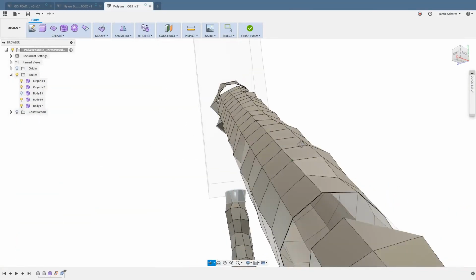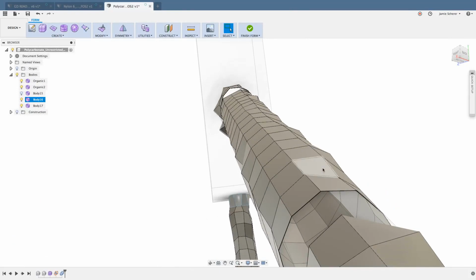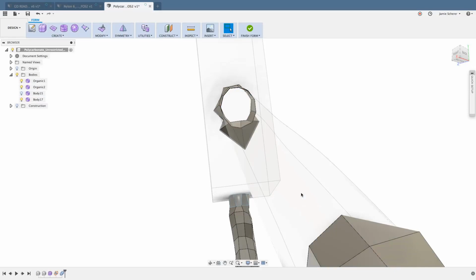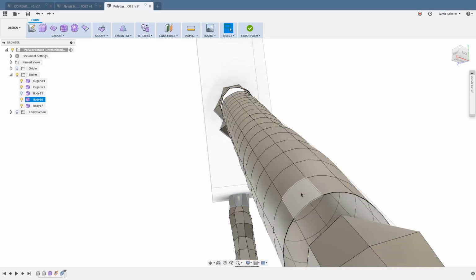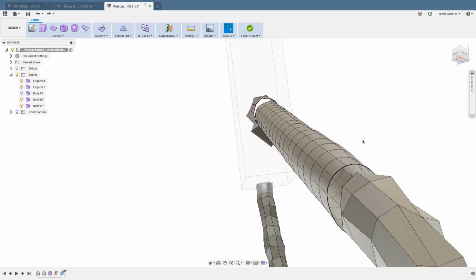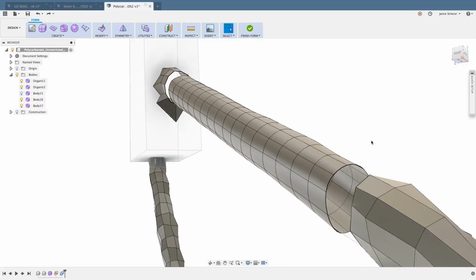Now, I think I might have to flatten out one more set of faces, but again, the goal here is to force some symmetry back into the object, similar to what I did before, where I deleted the body and then re-bridged the body. This is just another way that you can come in and rebuild some of the geometry that's not perfect, not incredibly smooth, or maybe needs some work in the Sculpt workspace.